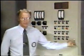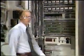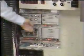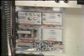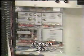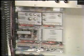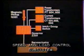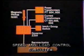shut down immediately. Now, another subsystem located inside the control console is the speed and load control subsystem, or governor Z251. Z251 is located here, lower in the console area. The governor panel includes an amplifier, ramp generator, load sensor, and speed sensor. Now, this subsystem has 2 input sources, one for engine speed and one for load.